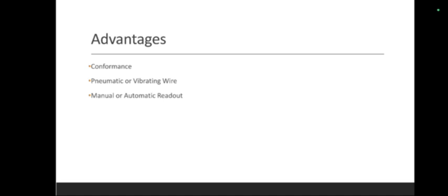The total pressure cells are embedded in fill or mounted on structures. The infill cells are often installed in arrays. Each infill cell is placed in a different orientation and covered with hand compacted fill. On structures, the cell is typically placed into a recess so that its sensitive side is flush with the surface of the structure.